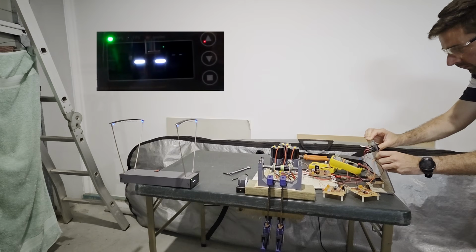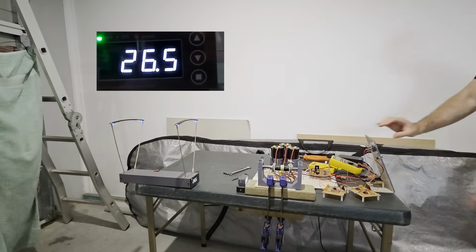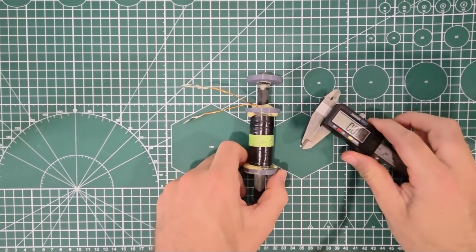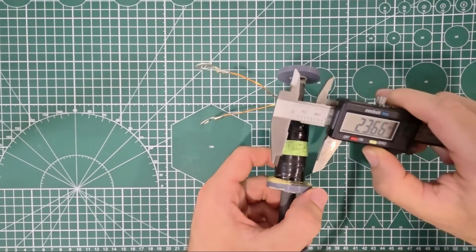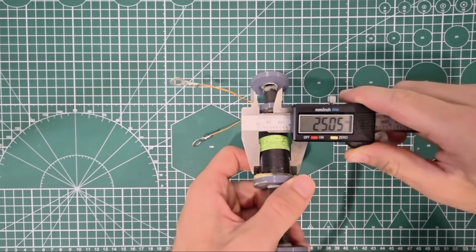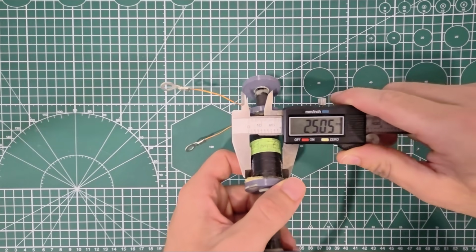This coil had its performance improve significantly from the increased current and reduced inductance, where its measured velocity increased by 4.3% to 26.5 meters a second. What if we now increase the radius above the baseline coils, keep the same length, but use the increased 1 millimeter wire, so the coil has 6 layers by 56 turns?